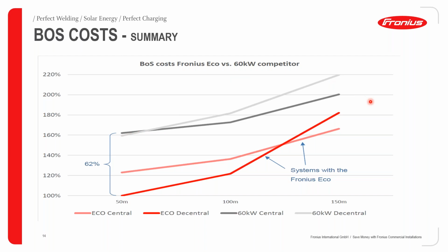And therefore, this is really something that you should think about when you are designing your systems, and ask yourselves the question: does it always make sense to use a big inverter? Especially for rooftop installations, the effort to take the inverter onto the roof, especially when the inverter is quite heavy, is a lot more compared to a lighter inverter. And you're also going to look at these details, how the effect of weight on BOS comes in, later in the presentation.